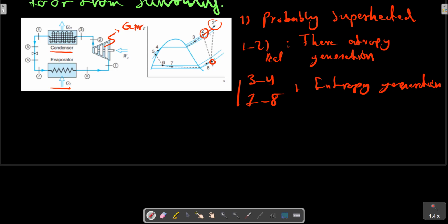The pressure of the liquid leaving the condenser will be less than the pressure of the vapor entry, and the temperature of refrigerant in the condenser will be somewhat higher than that of the surrounding to which it is being transferred. Usually, the temperature of liquid leaving the condenser is lower than the saturation temperature.